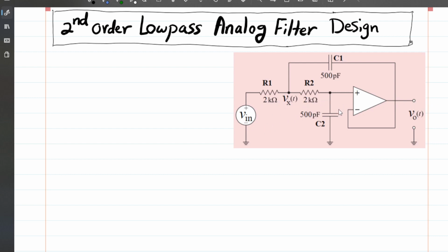At super high frequencies, for the same reason, the impedances being 1 over Cs, or 1 over jCω, with omega in the denominator super large, you can assume the impedances of these capacitors approach zero. It means these are roughly short. So at high enough frequencies, the positive terminal is shorted to ground.